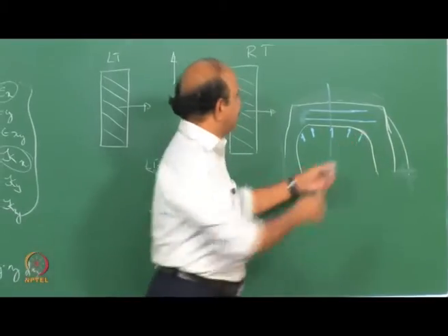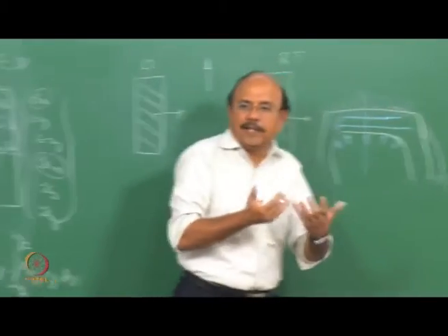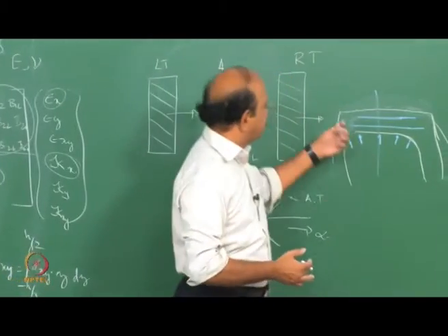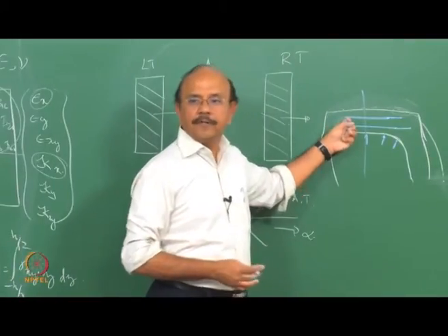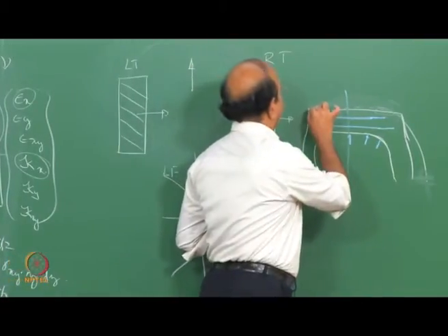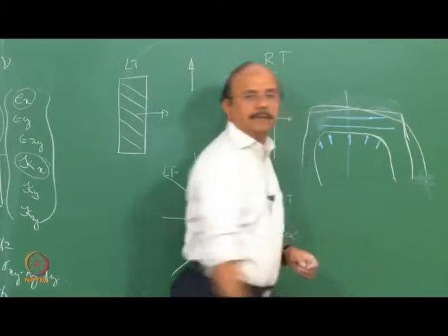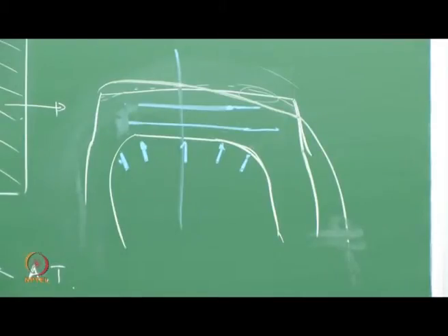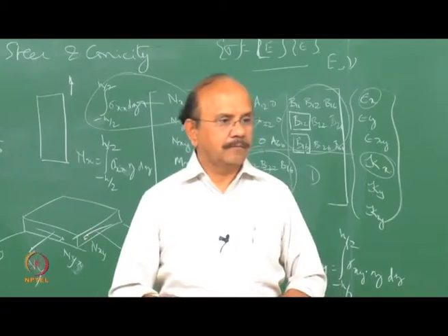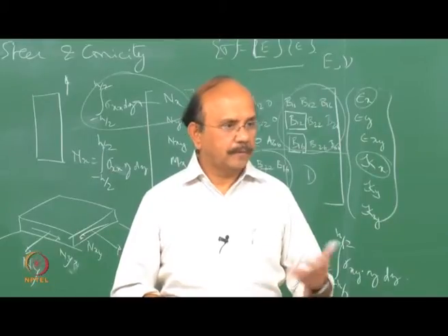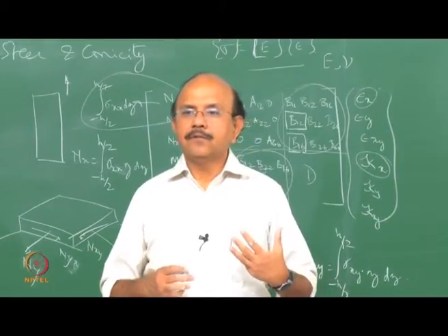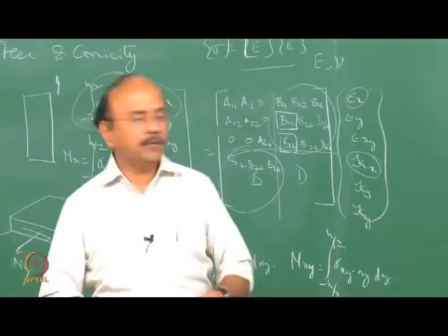So these material elements sitting here are not going to move to the same extent as to the left, and hence my tire is going to become something like that. In other words, my tire is going to look like a truncated cone. Right? So now you have a truncated cone.